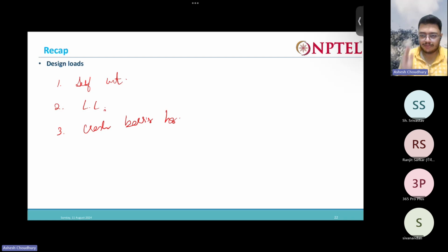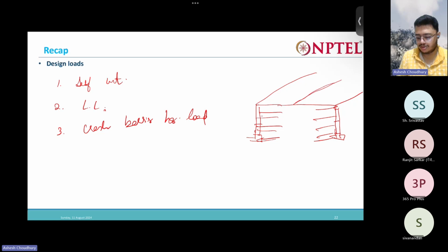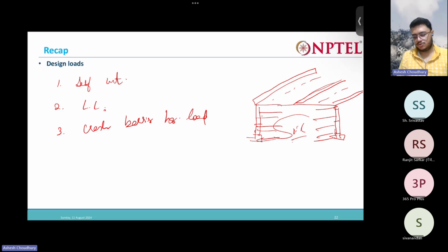So I'm drawing it like this. This is the soil wall, and again on this side one more is constructed back to back. This is the soil, and this part is reinforced, and here you have the highway that is constructed. These are your facing walls, and here you have the highway. This is the median, so you have a crash barrier here and here, and you have your 4-lane highway passing over it. Generally this is where reinforced soil walls are actually used. So the weight that is coming on this soil you have to consider.